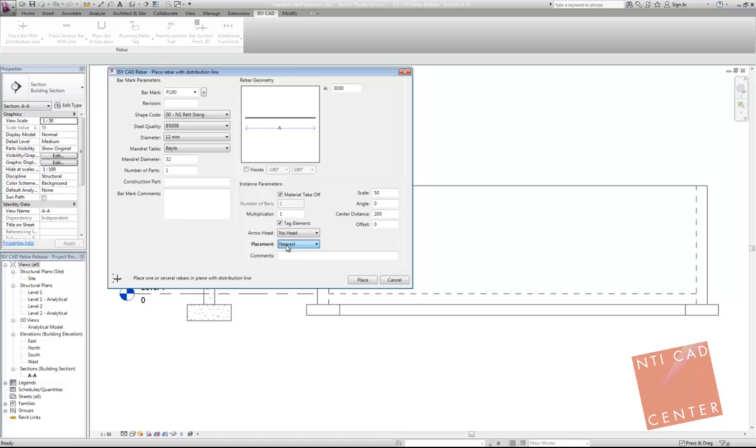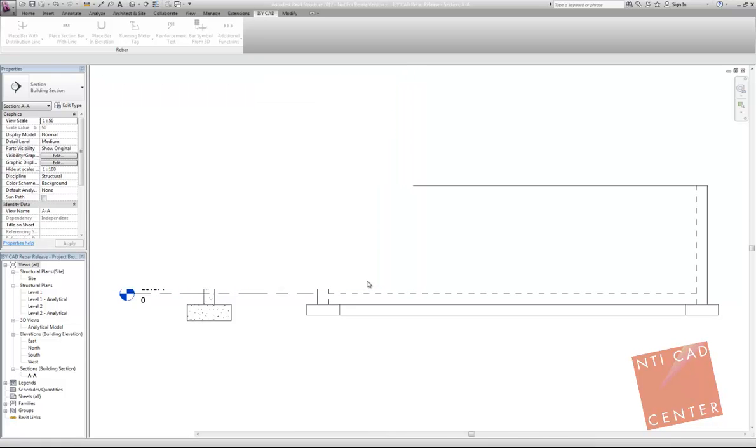So for example, if I will create this bar as nearest rebar, I would choose this one. So it will have respective symbols at the end of the bars. If I choose both vertical, for example, both horizontal dimensions, the rebar will look accordingly to this. So let's say I'm choosing nearest for this part, specifying center distance 200, let's make it 300 maybe, and let's click on place.